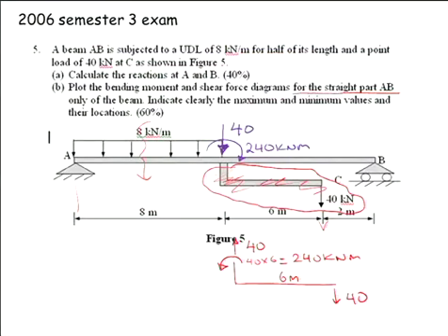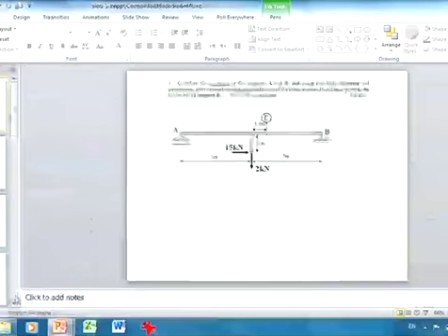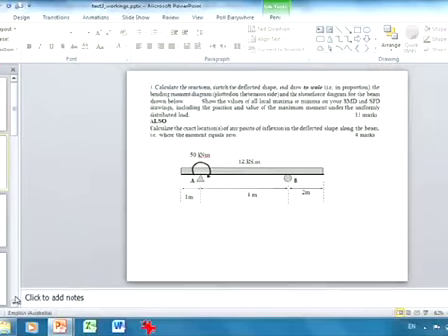In the test paper, when it came to drawing these bending moment diagrams, it said show values of all local maxima and minima. Oh, the local. That's a local one. Yeah. Basically, if you had to draw that, you'd put a parabola in and make the maximum value here and make it come up to a value here. So you basically need to put every value in wherever it changes slope, wherever it changes direction.